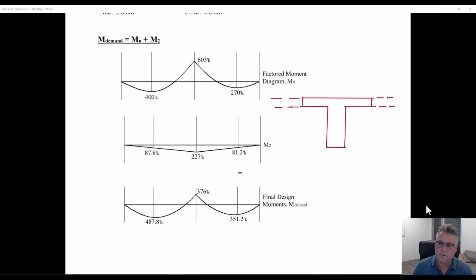Okay, so we'll take a T-beam. And really, we're always talking about T-beams. So realistically, this is only going to happen in a cast-in-place floor. We're only going to have indeterminate members when we pour the concrete in forms and make multiple spans. So if we're talking about a beam system, we're talking about T-beams. So what that means is that we'll have negative moments, and for negative moments, the steel is up on the top. That's how that's going to get resisted. And for positive moments, we're going to put steel down here, and that's how that will get resisted.